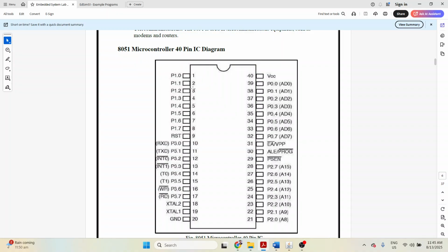But along with that, what we have to discuss here is very important. If you observe carefully, this 8051 IC is a 40 pin IC. Along with that, there are the VCC and ground pins, which are the supply pins. The most important point is that there are 4 ports, each a combination of different pins. Each port has 8 bits, so with 4 ports there are 32 lines.